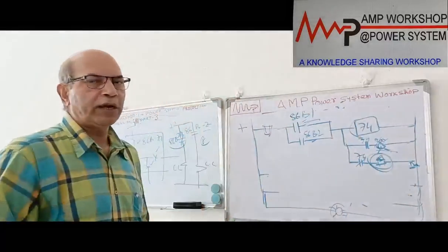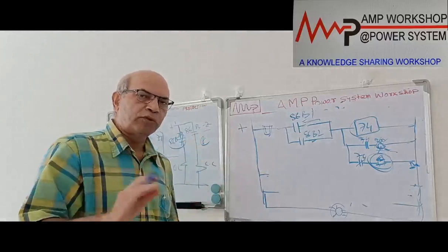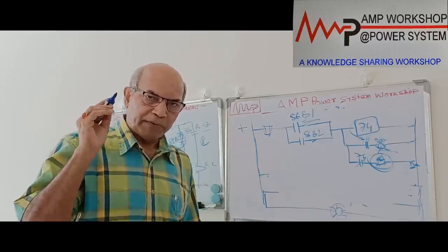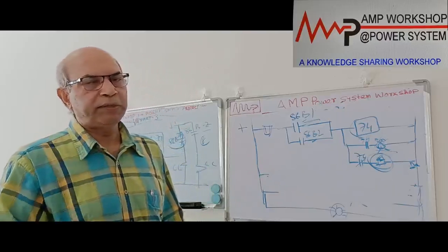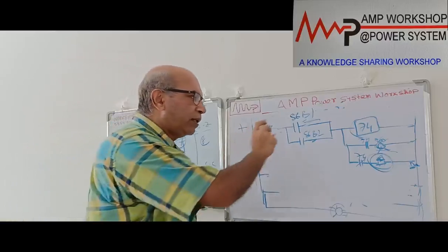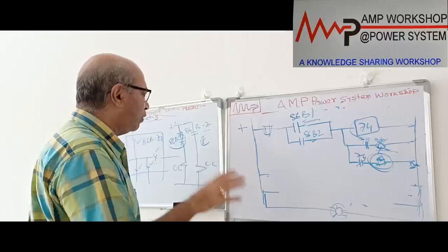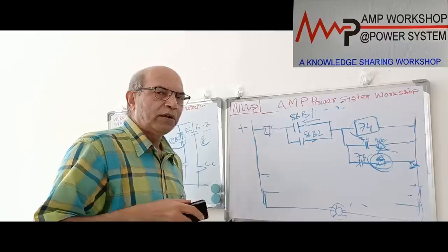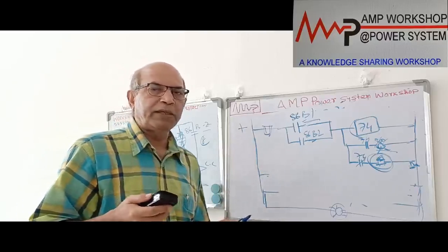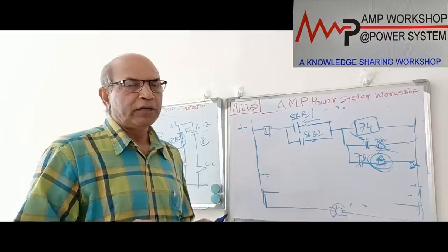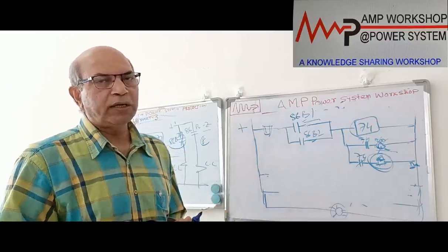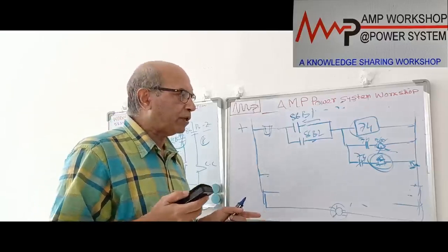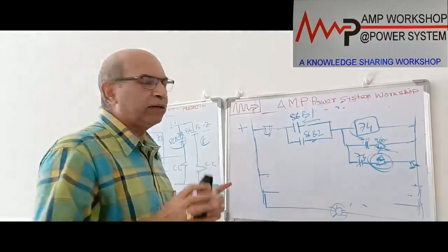So this way we can monitor this, and this scheme is common for all these features, that is current differential, bias current differential and high impedance differential. For all these three schemes, this requirement is constant. So this is a common diagram I draw for all this. If more number of busbars are coming, then the isolator interlock will also be required. So case to case we have to analyze in busbar protection, and we are discussing just a basic way how we can do this.